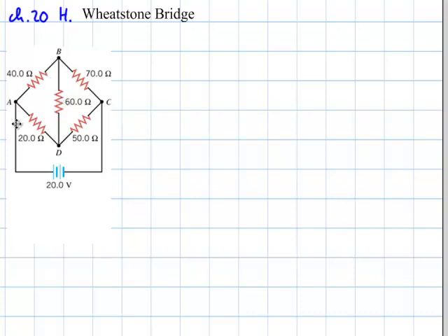For example, you could say that the current flows through here and through here, so despite the junction here, this could be kind of in series and parallel with this one. But then again, the current could flow through here and there, and it kind of looks like these two are in series and parallel with that one. So you cannot make a decision on it, and therefore the typical series-parallel combination circuit analysis is not going to work on this one, and it has to be Kirchhoff's rules.